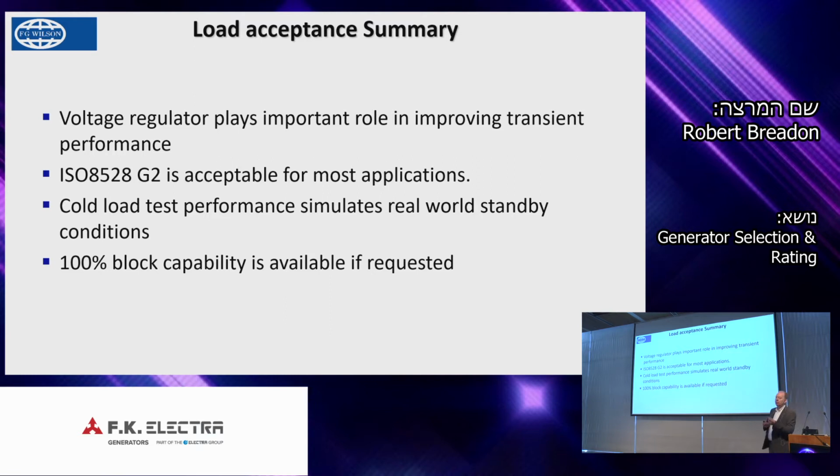We had an application with a liquid gas pumping station a few years ago, and the electric pumps in the gas had to start within 5 seconds or 6 seconds. It was a very quick start, and they had very tight criteria on the voltage dip and the response. And when we selected that machine, it was selected against that particular requirement.